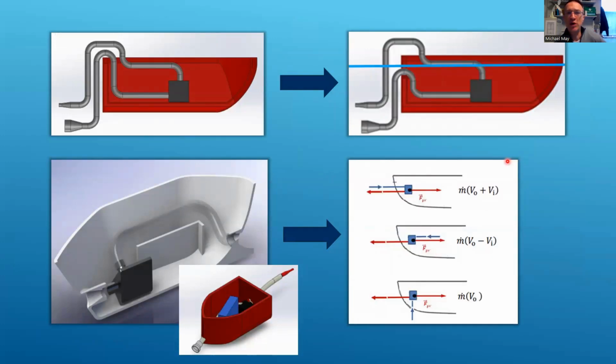So I mentioned the water line previously. You have to make sure that the inlet pipe is below the water line so that it gets primed and flooded with fluid, so that it works. So in this particular case, it's too high going over the back. It's unlikely to be able to be primed. In this case, you're just about getting away with it.